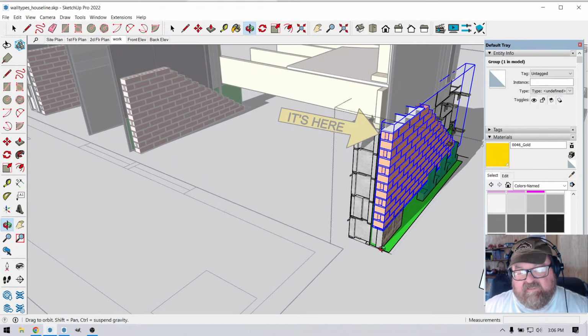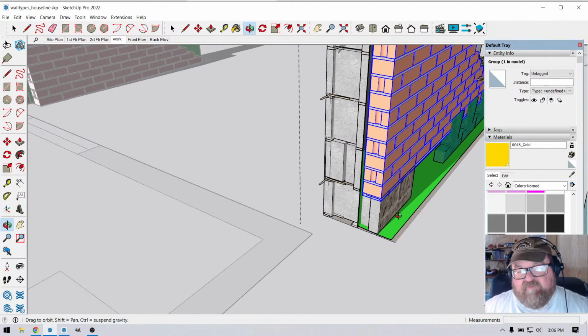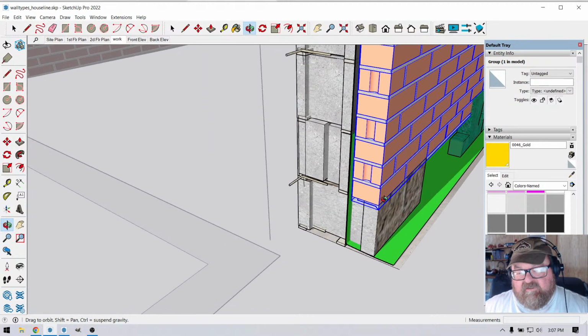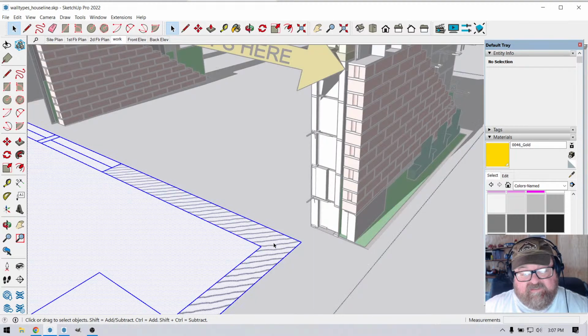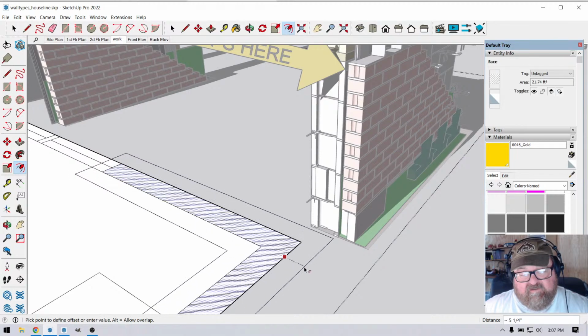You just need to allow, because when the surveyor comes back to verify the foundation survey, he's going to place his rod somewhere on the corner of this brick. When he does the foundation survey, he will come back. So this would be offset.